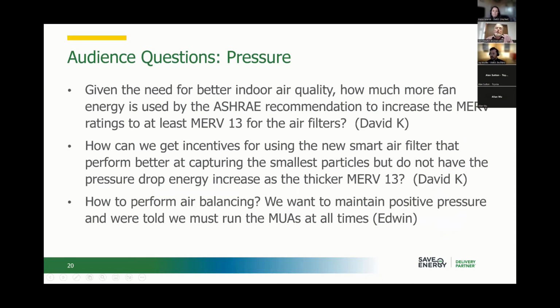Well, yes, the whole move to getting tighter and tighter on your air quality issues means having filtration that is simply that much more restrictive. There's no question about that. I don't believe actually, and I think that previous slide showed that, and we'll get into that with David, I think it is at another point here, but there isn't really that much difference between a MERV 8 and a MERV 13 when the filters are new. I think the one is maybe 25% more, but remember, it's only one part of the whole system here.